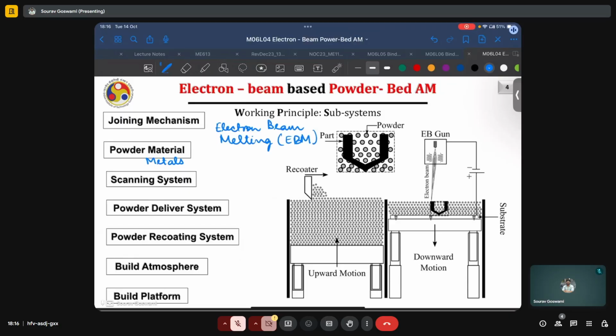When they, with such great momentum, collide with the target surface, they transmit this kinetic energy into the system, which may manifest in the form of heat and may melt the target surface or the beam or the powder particles or the wire, whatever as the case may be. However, since these particles are so light, if in their path from emission to reaching the target surface, they encounter other heavy molecules, they may be scattered away and may not reach the target surface at the desired flux. And so, we must ensure that their path is clear, and this may only be ensured in vacuum.